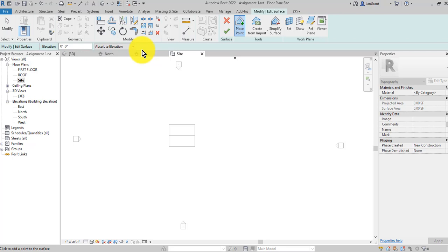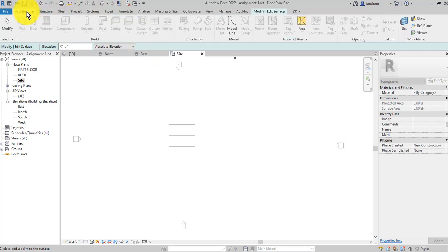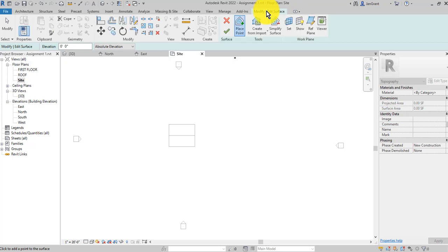And when you're in a sketch mode, guys, if you're in any of these other tabs, everything's grayed out. This happens so often. Students go to the architecture tab and want to start drawing and they're still in sketch mode. So look for that modified tab that's colorful and go back to see that you're in the sketch mode. Now guys, we're going to stay in the sketch mode for every one of the different elevations for the site.